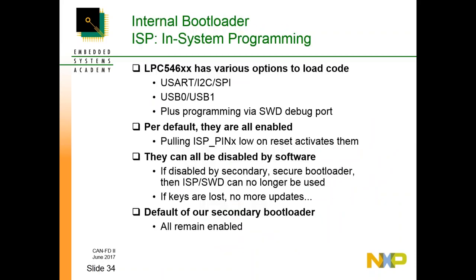Well, thank you. I would like to continue here on the internal bootloaders available on the chip, because if we talk bootloaders, of course, we have to review what's available internally. And the guys at NXP really have enabled almost everything available here. As you can see, the in-system programming internal bootloaders work with UART, I2C, SPI, both USB ports, and of course the regular debug port is available.